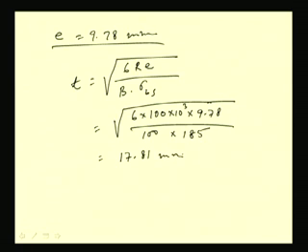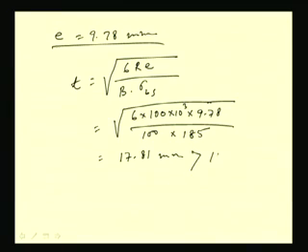That means the thickness required for the seat angle is 17.81 millimeter, but we have provided 10 mm because ISA 100 by 65 by 10 we have used. So it is greater than 10.